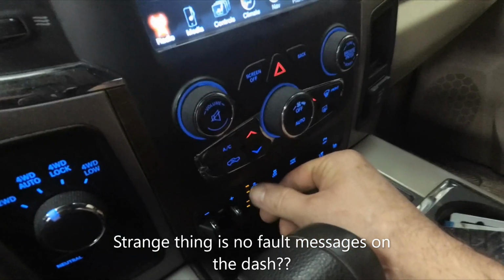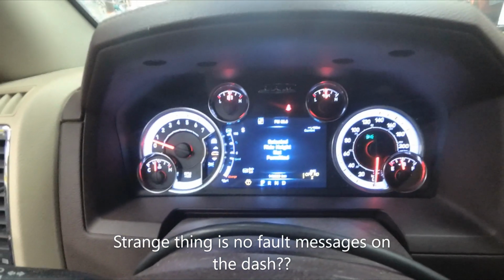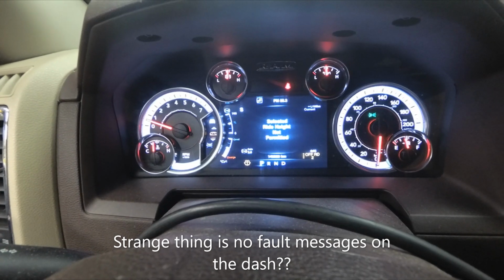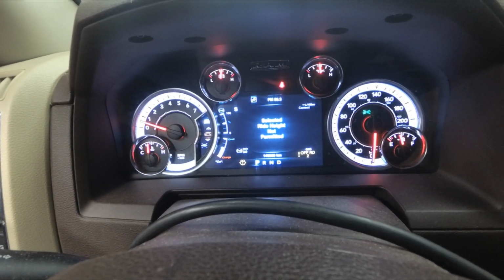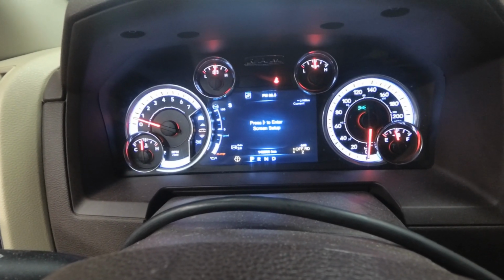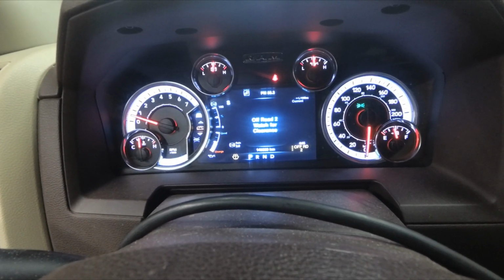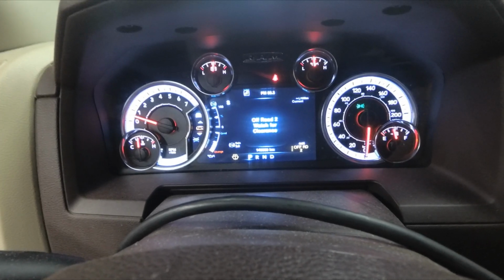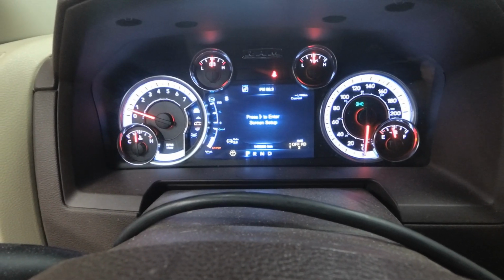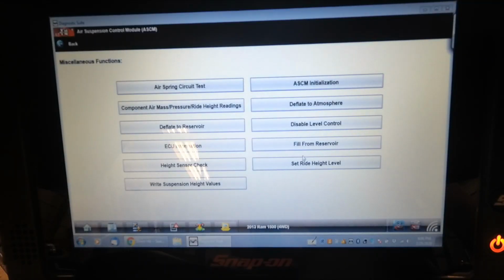So right now it shows off-road 2. If I use the suspension control buttons, press it up once, it says ride height not permitted. If I press it a second time, I can get it to say off-road 2. I'm going to press down. Nothing changes. Pressing up now. Off-road 2, watch for clearance. But this display still says off-road 2. That's where I had it, and I'm going to try and activate that feature again. So we'll try this one more time.